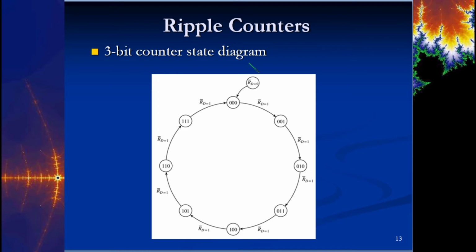All right, and then you have to account for the fact that if somebody already has 45 cents in and the last coin they put in is a quarter, that's going to be 70 cents. So you still have to account for some states that are above 50 cents, right? Because then you have to do something about the change. So when you look at the state machine of one of the old Coke machines and you look at where all of the lines go, here it's pretty simple, right? As long as the asynchronous reset stays high, you just keep counting in order.